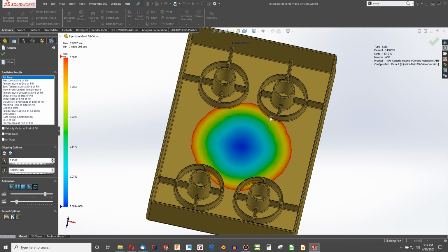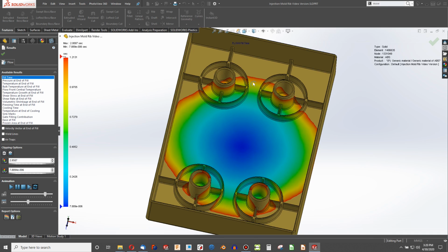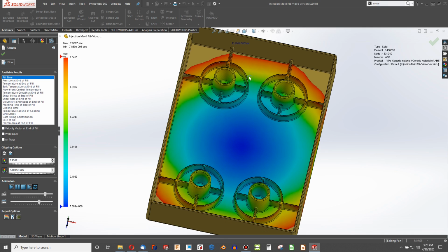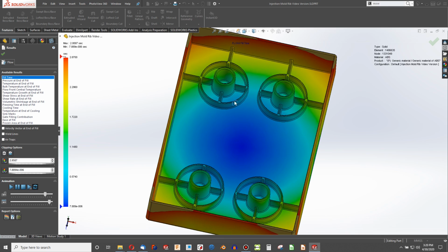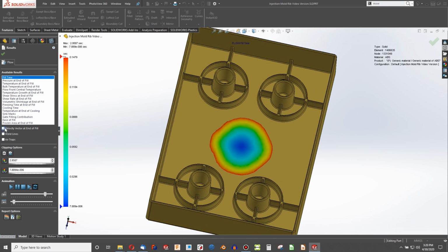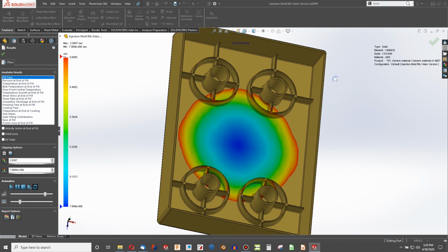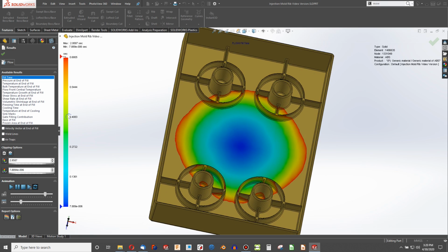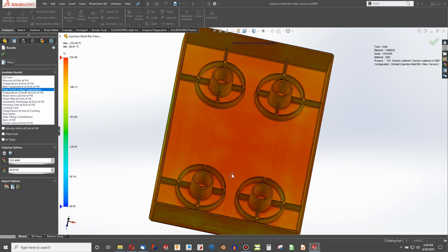As we mold from the center, you can see these ribs are filling up very quickly and very nicely. The flow front is not really hesitating in this simulation, and we're able to flow with pretty good consistency all around. Between recording and running this, I think my screen is a little bit blocky here, but if I look at flow front central temperature, we're at a rather even temperature throughout.